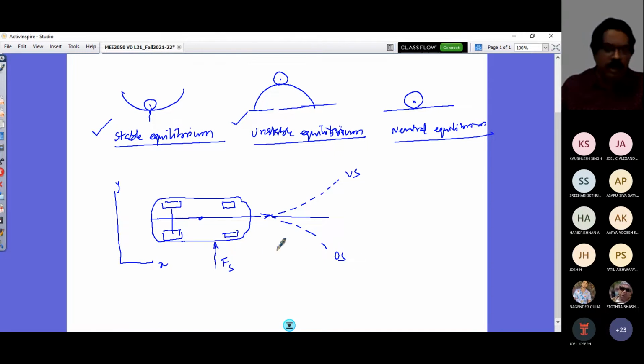So that is your oversteer condition of your vehicle, and that would take it to an equilibrium called an unstable equilibrium. That means this oscillation cannot be there, and suddenly your vehicle would be drifted and it will be spinning about your vertical axis, and the state would change, and the position of your vehicle on the road is arbitrary, and that is what is called an unstable equilibrium. So a vehicle is in unstable equilibrium because of the oversteered tendency. Maybe the vehicle is a rear engine mounted, rear wheel drive vehicle, naturally an oversteered tendency vehicle.